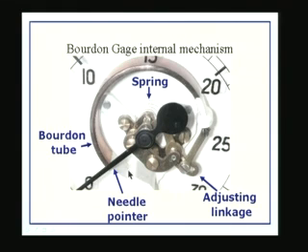and the inside is communicated to the inside of the tube, which is sealed. To the sealed tube, we communicate the pressure to be measured, and of course, the outside pressure is the atmospheric pressure, or in some cases the outside pressure may be a different pressure. We can use this for measuring the differential pressure or the gauge pressure. By now you will realize what gauge pressure means.